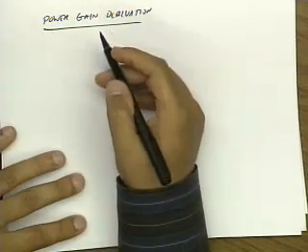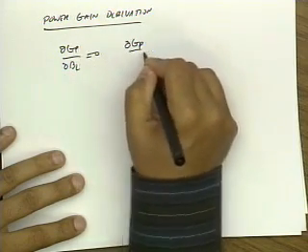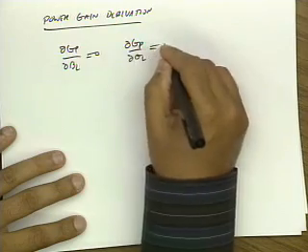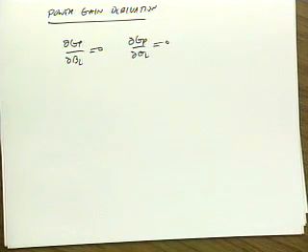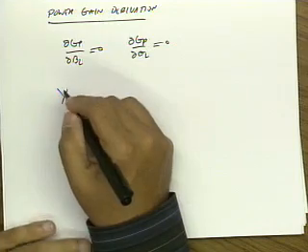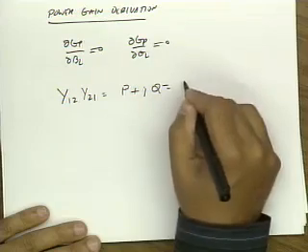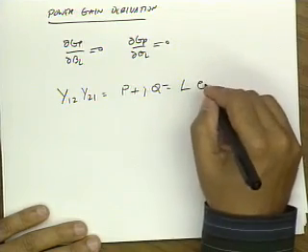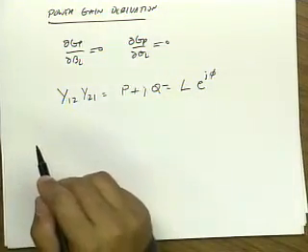So what we're going to do is take dGP/dBL equal to 0 and dGP/dGL equal to 0. I respect you guys. I know you can do algebra, so I'm not going to bore you to death, but I'll give you the final answer. Let me define a couple of useful things. Let me define the product y12 y21 as P plus jQ, or some magnitude L e to the j phi, where phi is the phase of this product.